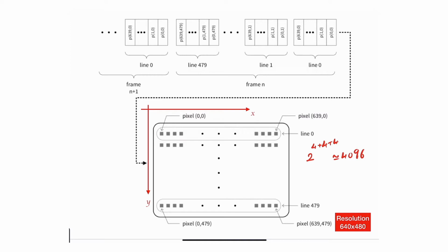The reason we're restricting ourselves to 4 bits is because the hardware on the Nexys board, or even the Basys board if you're using that, basically allows you to use that. However, in our code, we're going to make sure that these are parameterized so that if you're using a different board, you can easily modify it so that you can use the whole byte.